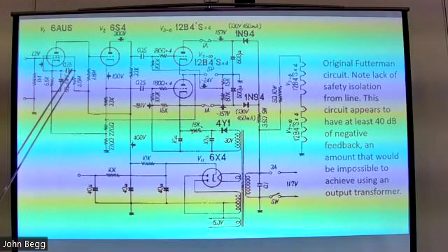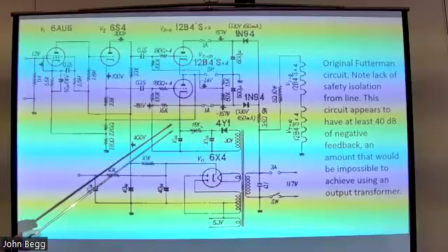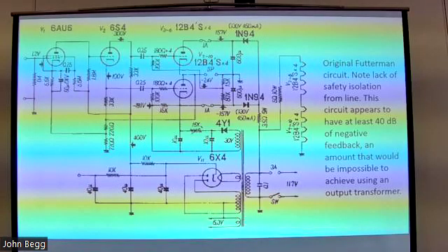He doesn't have to put any extra diddly capacitors in there because this works perfectly. All the other impedances in this circuit are low, so there's not going to be much phase shift. So this is really ideal design. I mean, this is really good. So even though he screwed up on the power, this is really good.